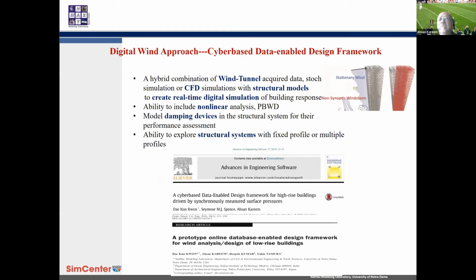Digital wind approach is a cyber-based, data-enabled design. This connects to the multiple pressure point fluctuations which we have. What it does is it provides you a hybrid combination of wind tunnel and CFD with structural models, as earlier Dr. McKenna mentioned. This creates real-time digital simulation of building response.